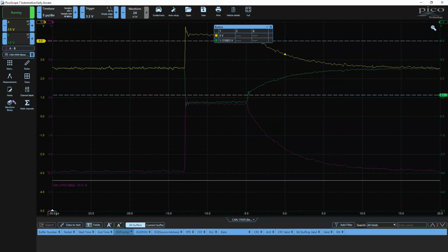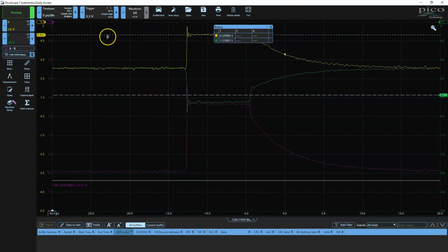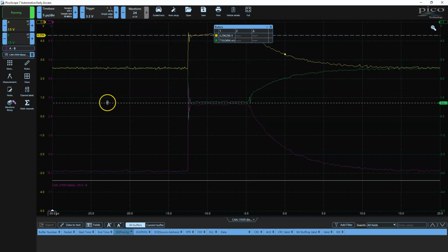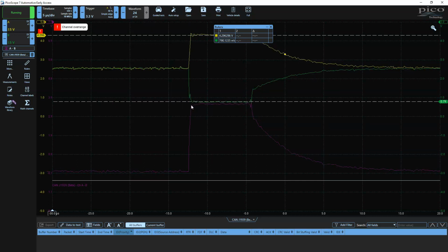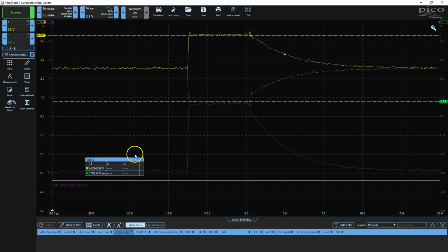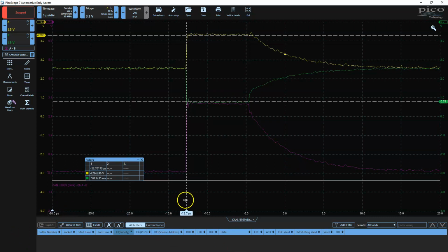A couple of things occurred, not that it's real important. The voltage increased, right? Now I'm basically driving into only the other CAN transceivers that are out on the network. So this voltage increased. You can see the thing that's happened here, and this is what I wanted to show with the 8 microseconds of bits in the beginning. So let's pause this, where we have the start of frame, and a message with a high priority, a priority of 3. So here's my 8 microseconds.